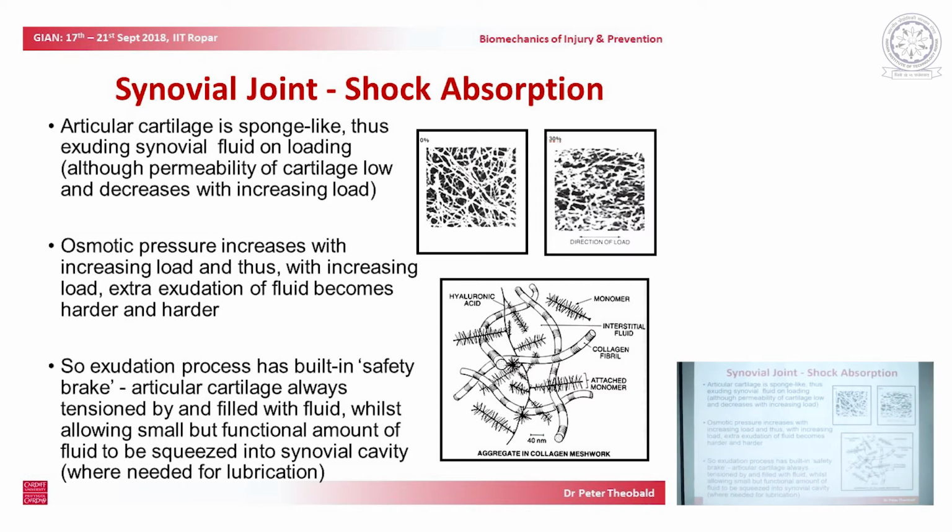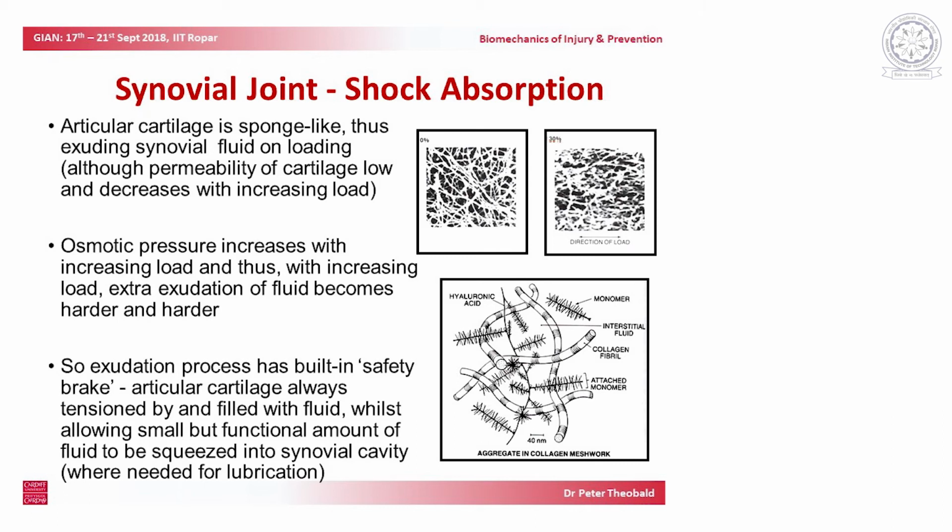And it's quite challenging because of its structure and because of its ability to deform. And it's this deformation which is key to its functionality. As we said, if we look at the little picture on the right, if we weren't to have deformation in the articular cartilage, we would have the same load going through a far smaller contact area, and so our contact stress would go up. Where we have greater contact stress, then we have greater risk of failure.